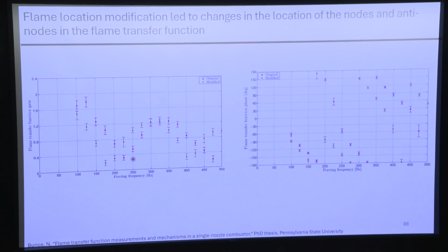And so now we have two different disturbances that are moving relative to each other, but we've just offset them. In the case of Paul Police's work, we've offset them by changing this convective velocity. In Nick's work, we changed them by just changing the location of the flame, and you get the same result, which was really, really nice. So this is good experimental confirmation in more realistic geometries, right? This industrial hardware flows like at 30 meters per second, and you can see this really clearly, which is very cool. Questions on that?